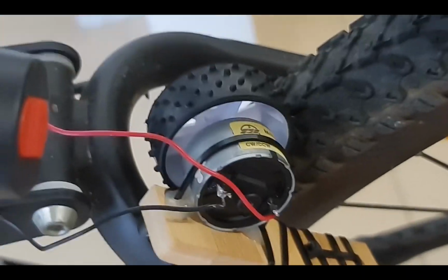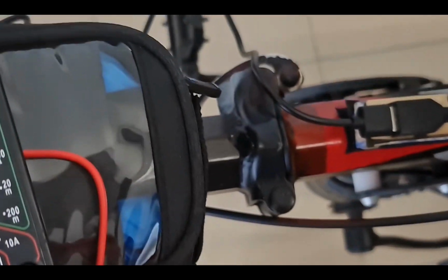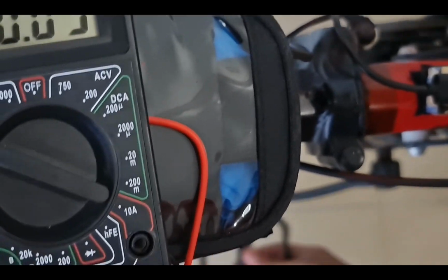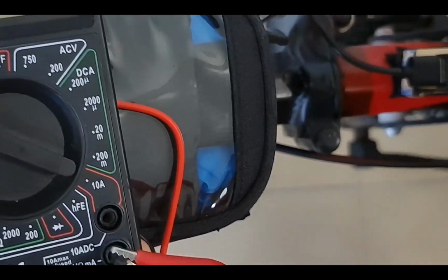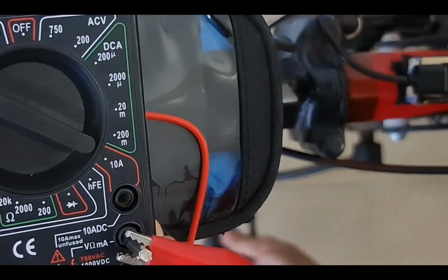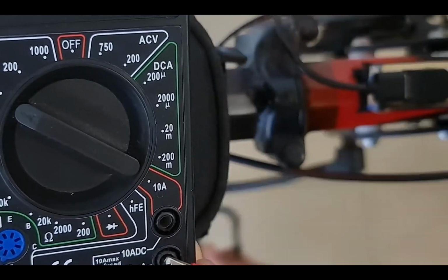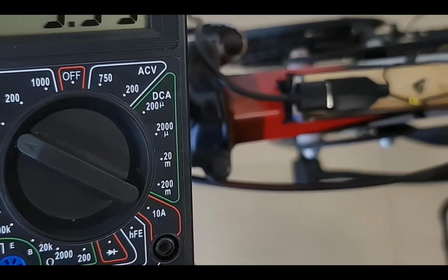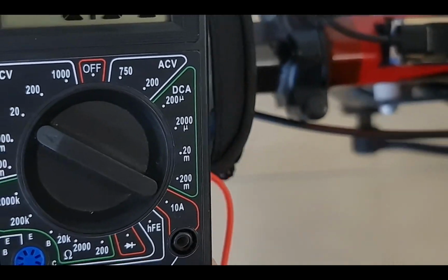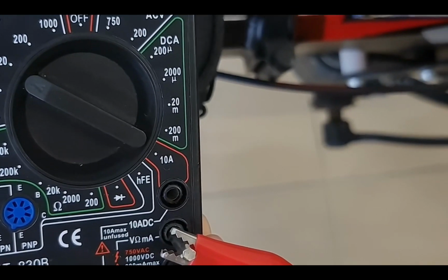In this next clip, I use the voltage regulator LM7805, which outputs 5 volts, and it shows an average of 4.4 volts. So the output voltage is suitable for a normal USB load, which needs 5 volt output and 1 ampere.